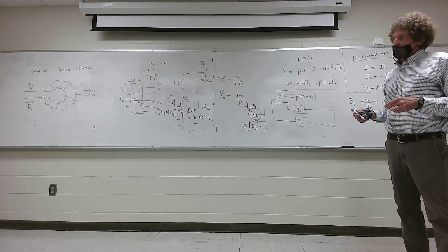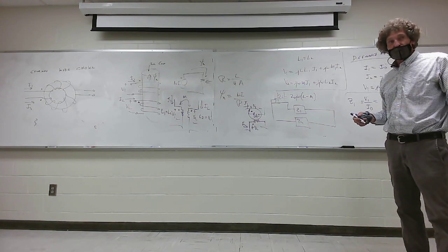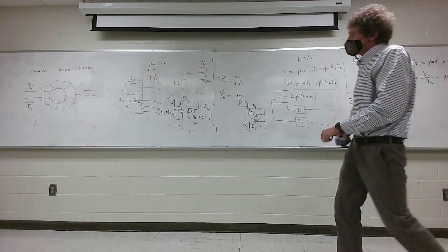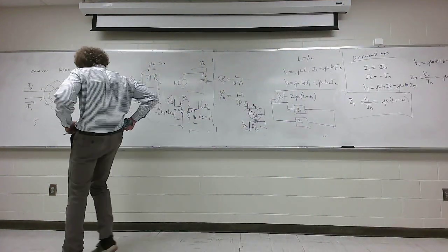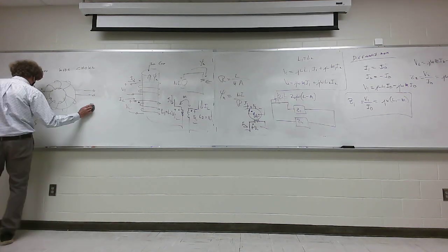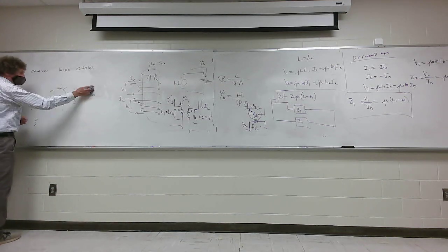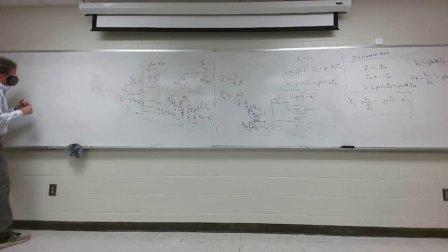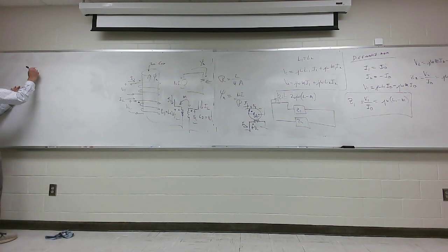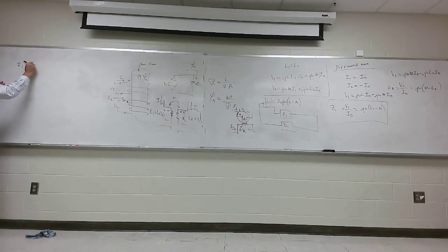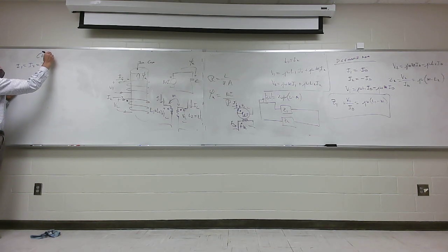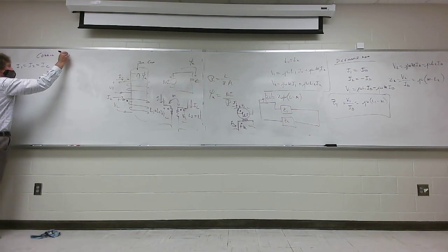So the idea for a common mode choke is you want no impedance, no limit to the actual standard differential mode. Now, when it becomes something where you have a common mode signal, when I1 equals I2, I'll put it over here, and this is important. So when I1 equals I2 equals I, and you can call it I common, this is a common mode current.